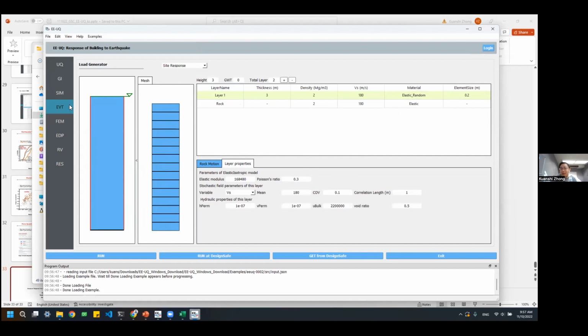That perhaps would be a more detailed version of the local geology, and maybe you will use the depth to the rock to define the soil column. Maybe you would like to use the water table, and use the shear velocity to do an inverse problem to see what might be the right parameters to define those material properties to simulate the soil responses. Is that the question, or maybe correct me?